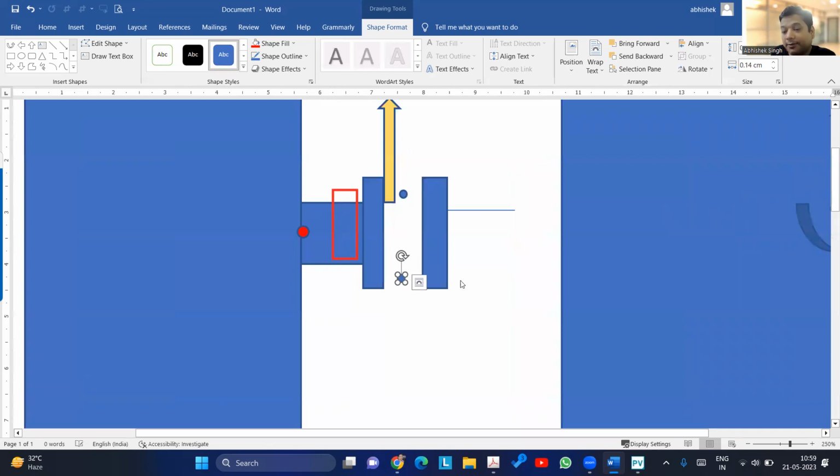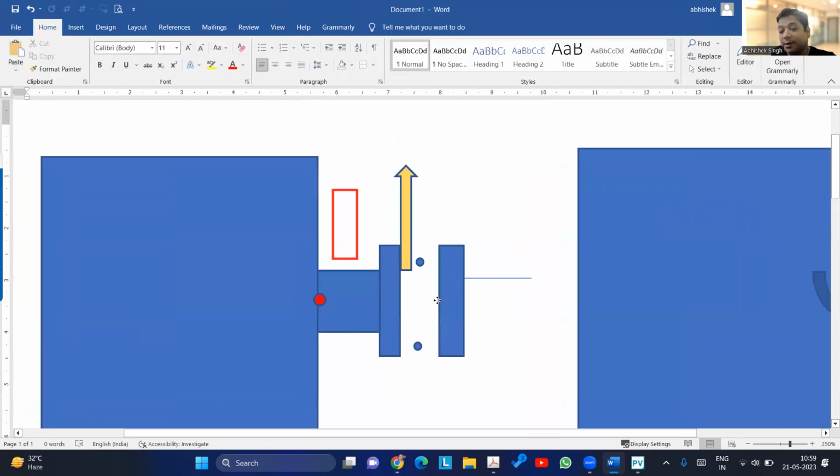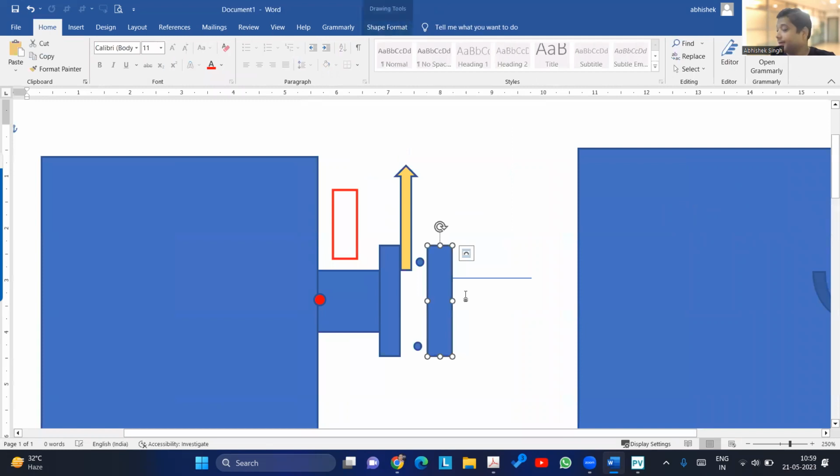Yeah. So this is the gasket. Now, radial load P. Do you think anything is happening with it? See, finally, we are worried about the leakage. Right? The purpose of this flange joint is to perform and contain that pressure. Not only retain its shape, but the main purpose is to avoid leakage.